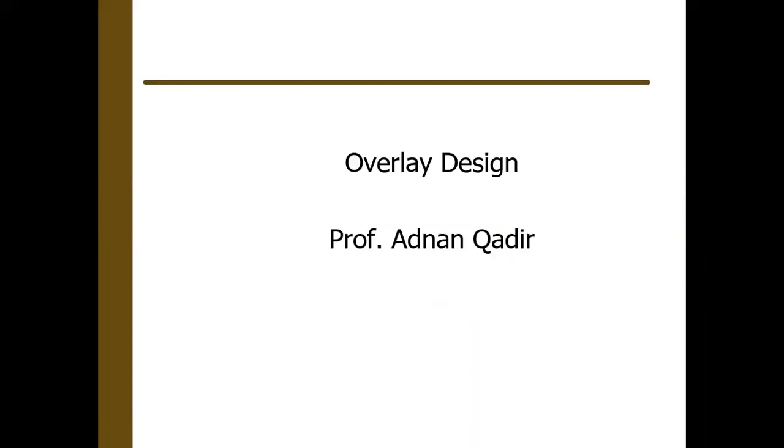Bismillahirrahmanirrahim. So today our topic is the overlay design of highway pavement. This is Professor Adnan Kadir. Now, what is an overlay? An overlay is an extra layer of a pavement that is laid either on a disintegrated surface to improve the structural efficiency of the pavement, or it can be a 2-inch layer normally to rejuvenate the pavement surface in terms of its riding quality and improve skid resistance.